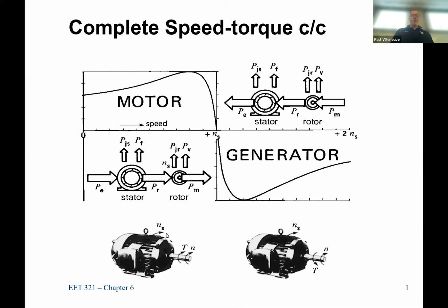One thing I'll say is both of these, if you look at rotation, they're both rotating. And if you're facing the shaft, they're operating in a clockwise direction. Look at the speed. The speed is also in a clockwise direction, but look at the torque. The torque here, it's a little hard to tell, but this would be the equivalent torque for the electrical power. So our electrical power is driving a torque that's in the same direction as the speed, which makes sense. It's a motor. That's where the power is going in. So it has to rotate the shaft.